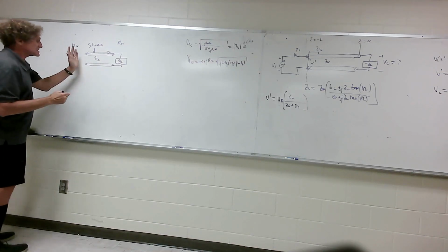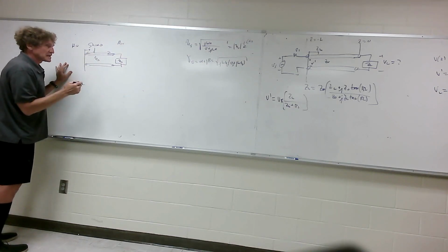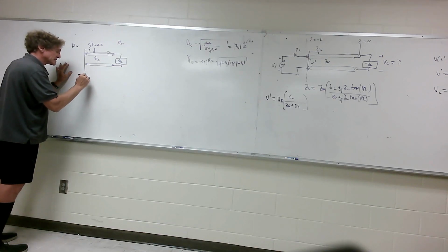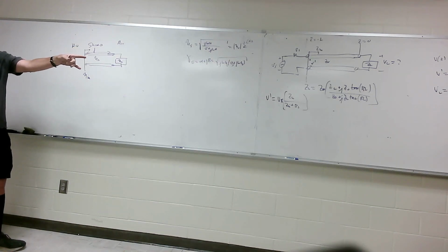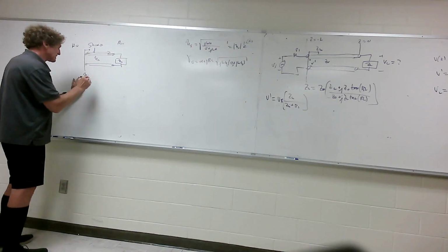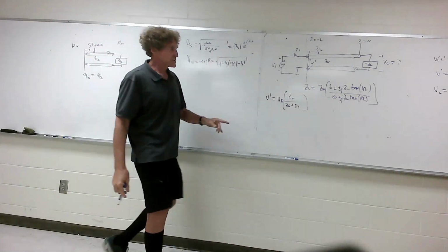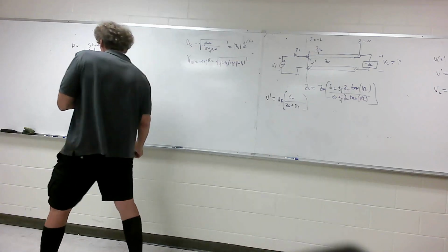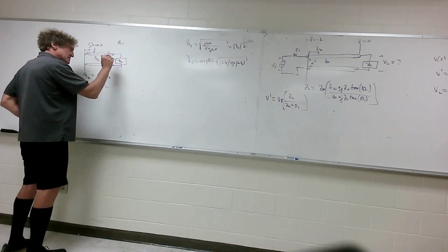Then, at this point, instead of having a Zn, now his book does use Z, but I'm going to say this point right here, we're going to have an eta n. This is the effective input impedance of the shield, similar to the input impedance for a short transmission line. And this is going to be equal to eta of the shield. The eta here has to do with the impedance here. This impedance is actually going to be complex. Then it's going to be equal to eta naught, that is the load impedance.